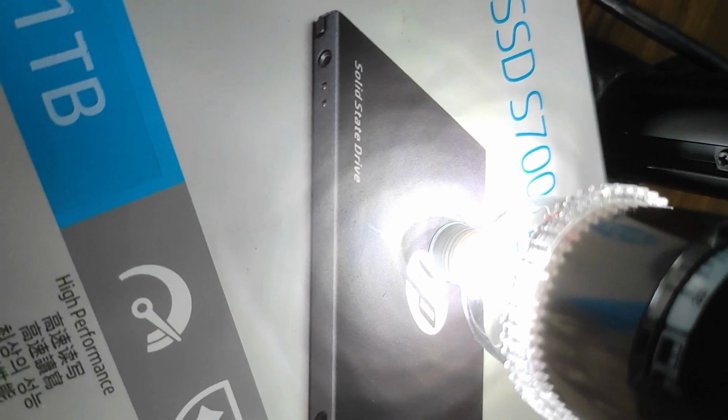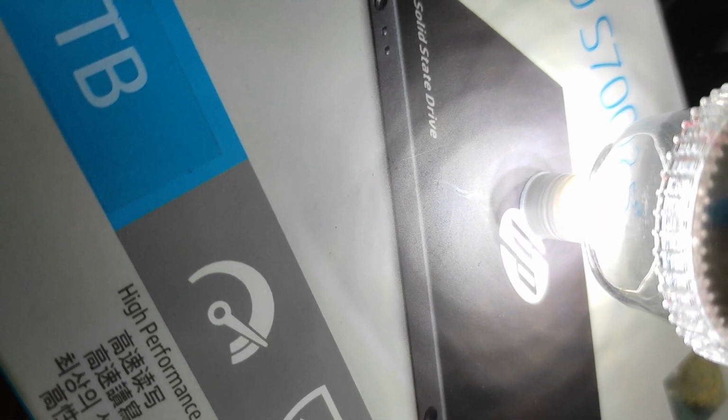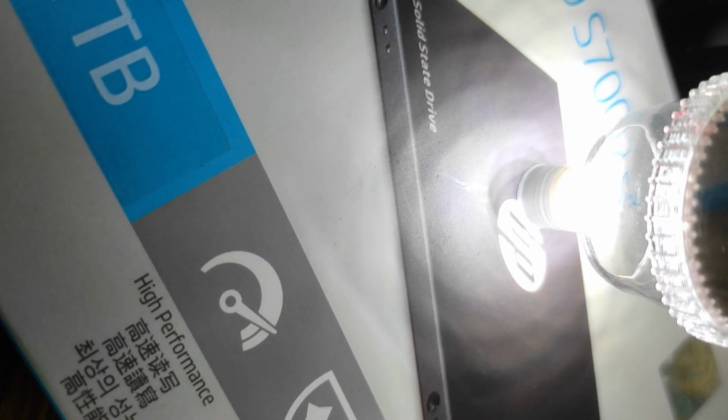I am measuring the dimensions of this 3D printed part by using a microscope. Usually in practice we measure all the dimensions of a 3D printed part by using a coordinate measuring machine, also called CMM, but right now I am only able to show you this. So you can see that this is the printed hole, and I will measure this.